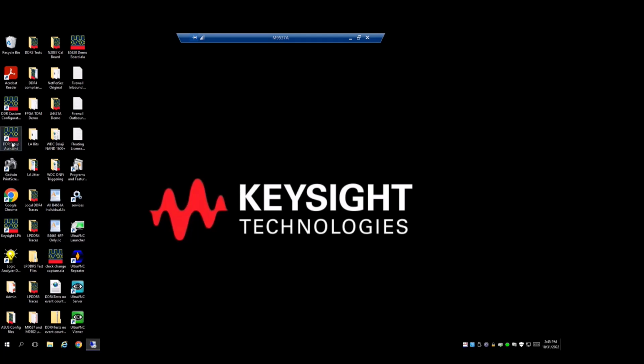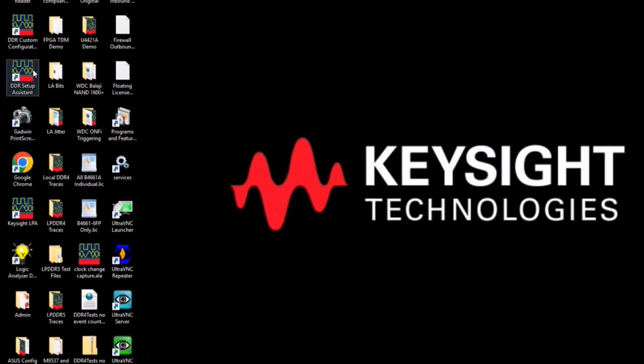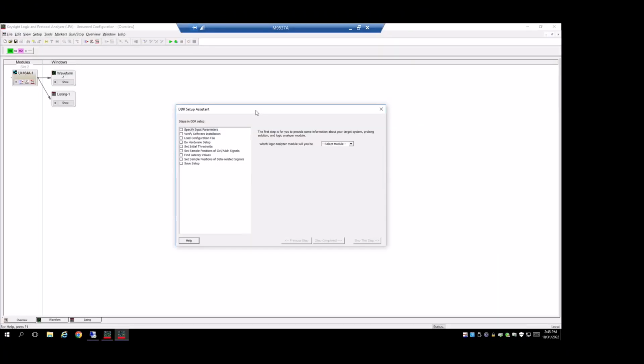Once the software is installed, you'll see the icons for the logic analyzer and DDR Setup Assistant on your screen. Double-click on the DDR Setup Assistant icon. This will start a logic analyzer session, and it will also start DDR Setup Assistant. If you have a logic analyzer session already started, DDR Setup Assistant will make modifications to that logic analyzer session. DDR Setup Assistant is semi-automated, and you simply step through the questions.